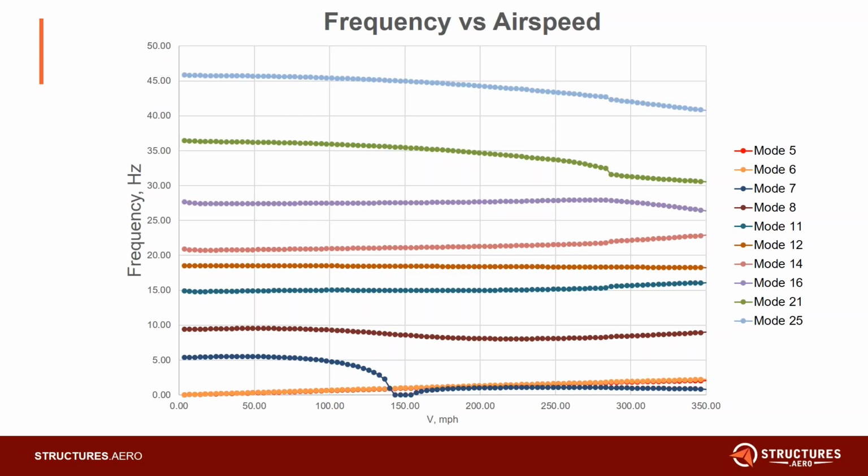And you can see it does become critically damped for a small series of points, and then that frequency curve pops back up. Often what that falling to a zero frequency, becoming critically damped, means is you need to look out for divergence. In this case, it's not too much of an issue, but it is something you might want to watch out for.